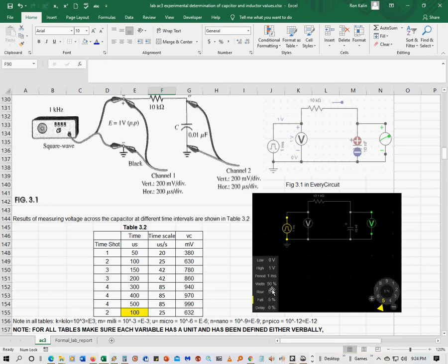The period, and then the width of the period that ends up being the positive part, or the part that is actually energized, and then the other part is going to be on the bottom part, and then the rise and the fall are the percentage of the slope. If you make these 0, it's going to go straight up and down, and the bigger this number, the more the slant is going to be to the actual square wave.